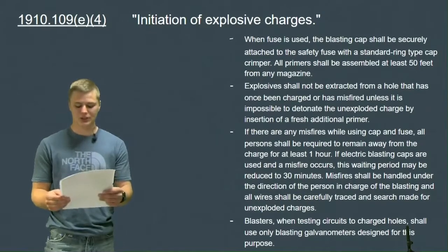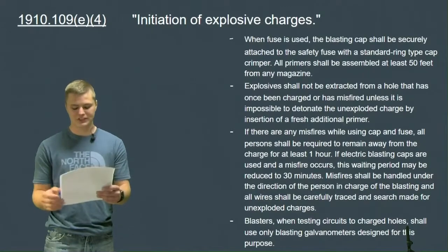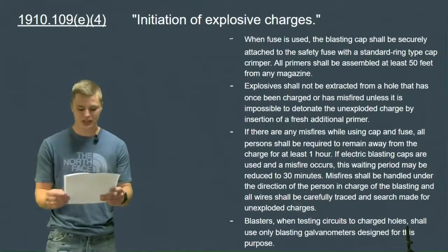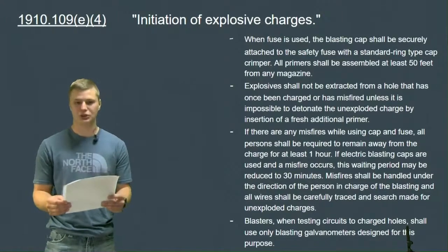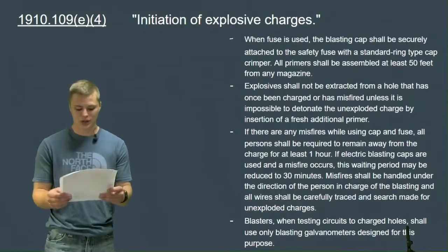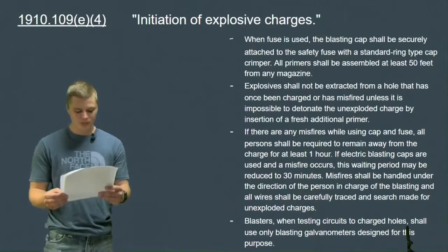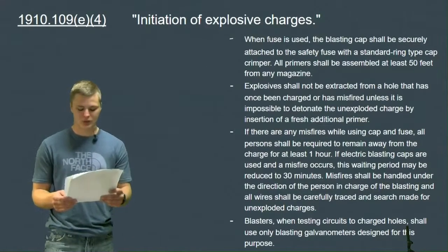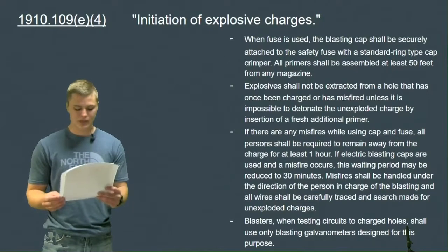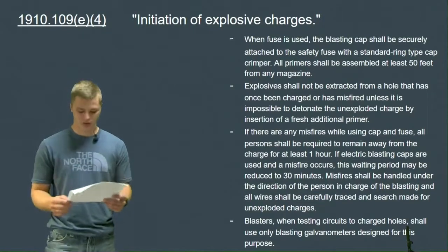Explosives shall not be extracted from a hole that has once been charged or has been misfired unless it is impossible to detonate the unexploded charge by insertion of a fresh additional primer. If there are any misfires while using cap and fuse, all persons shall be required to remain away from the charge for at least 1 hour.